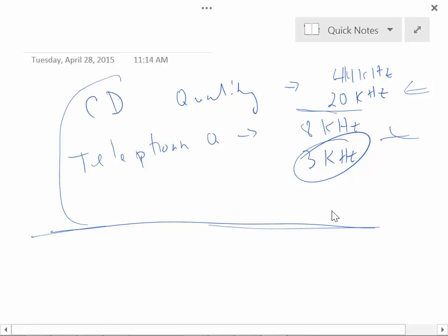Audio signals for CDs, for example, you don't hear noise, harmonics, say, on a piano that are above 20 kilohertz, but they exist. They're there. And if you don't band limit, you're going to hear them, and it's going to create noise, and it's not going to be a very good quality noise that you're going to enjoy. So that anti-aliasing filter is very, very important.